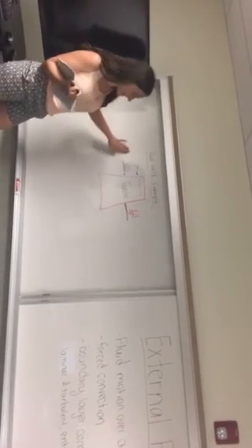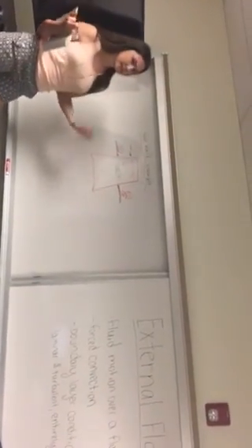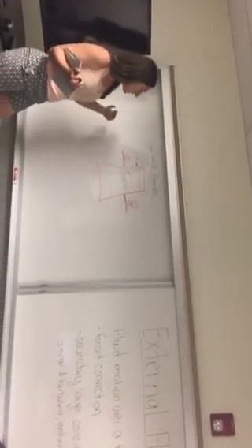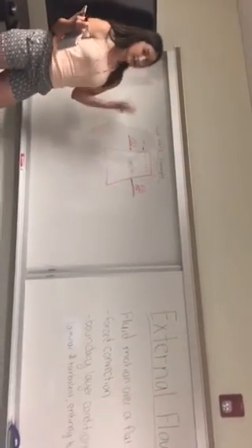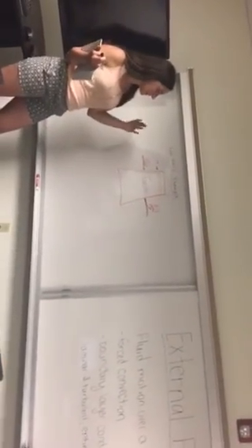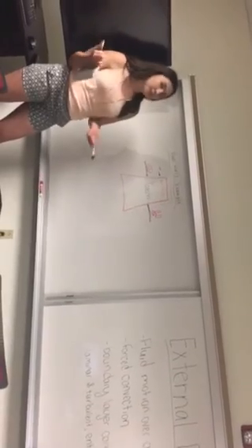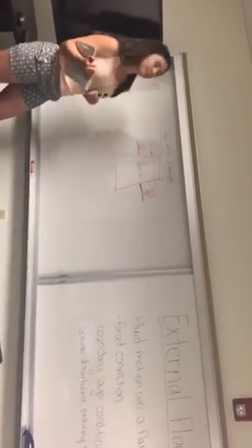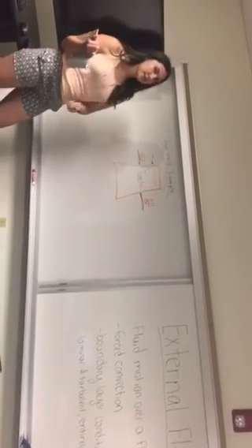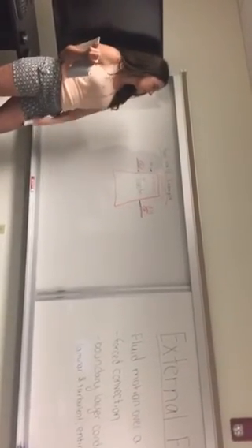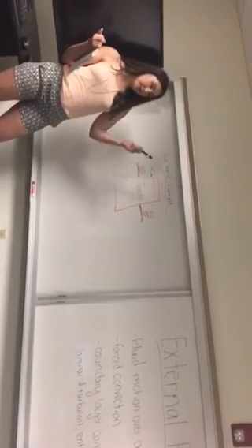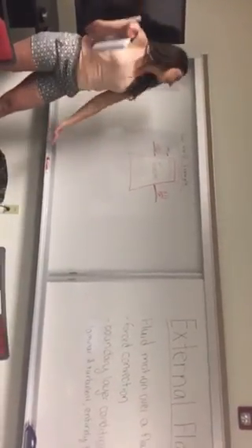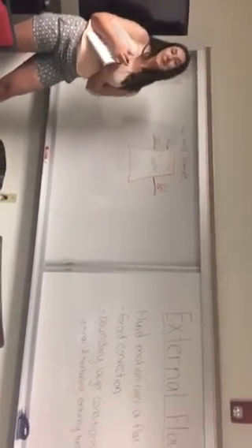Your bagel is just sitting on there, and you need to heat it up, so it's going to symbolize our flat plate. It's moving at some velocity into the toaster, and then the air is going to blow over it. If you know the temperature of the air inside the toaster and the velocity that it's moving through, you can use that and the temperature of your bagel to solve for Tf and get your values, and then you can calculate the maximum power that you wanted depending on how hot you want your bagel to be. So there you go, now we know about external flow.